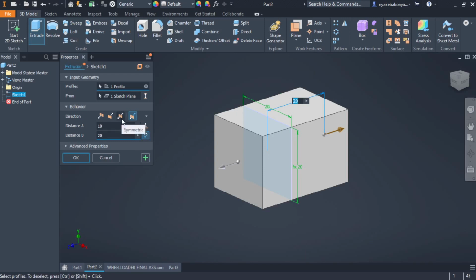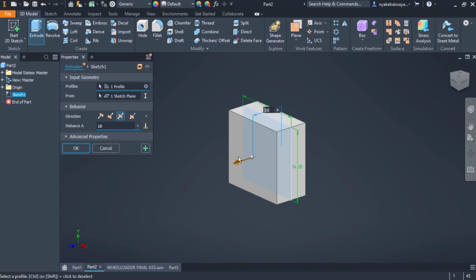Now, if we go to symmetric here, there are those parameters that we assigned, like the width that we created. If we want it to be a cuboid, there's this arrow here. You can click that arrow and then click list parameters. Now you see the parameters we created, length and width.